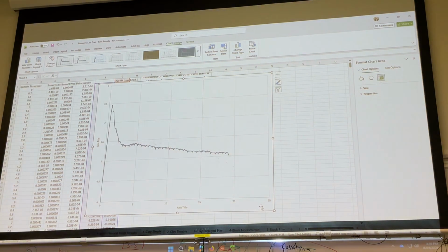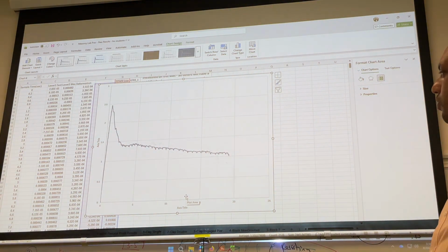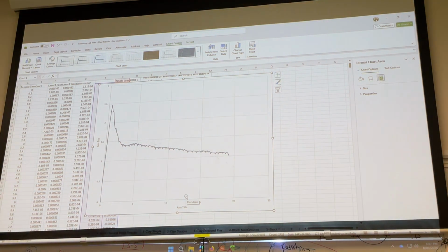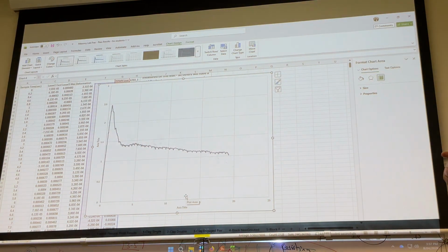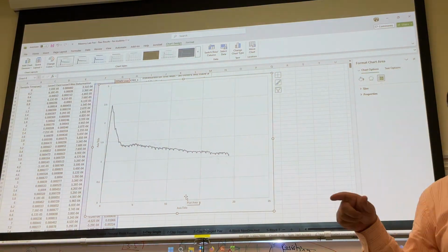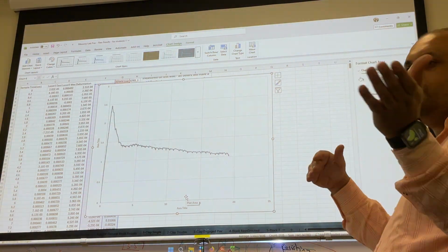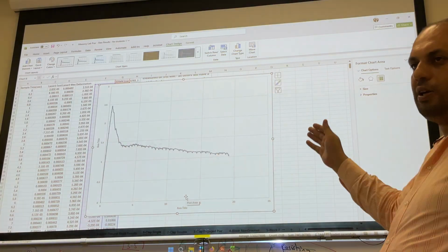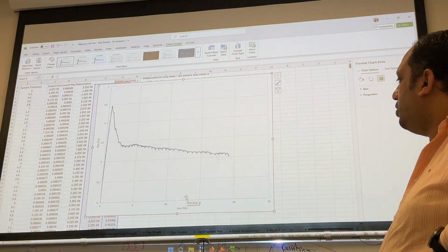Okay, so this is the load displacement graph for the first one. What is the maximum load? About 2.4. Okay. So if you have two lasers, it's because we have measured the two sides of the wall from the back. To get the one displacement, you need to take the average. So the first step, you take the average. Then if it is negative, you need to convert it to positive to make it to the right side. Then you select the two columns and plot the graph.